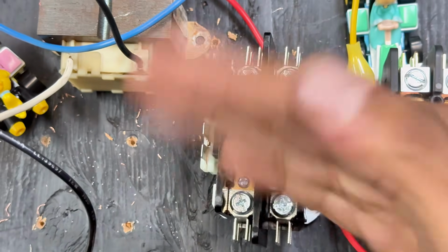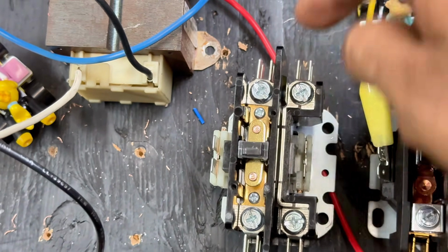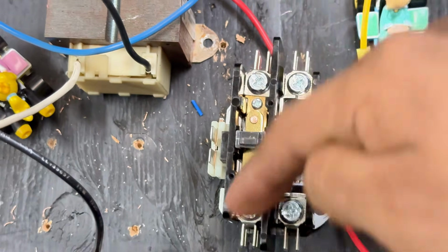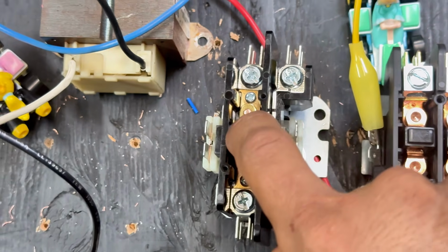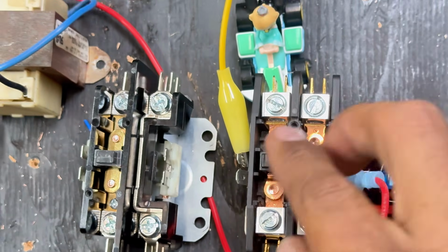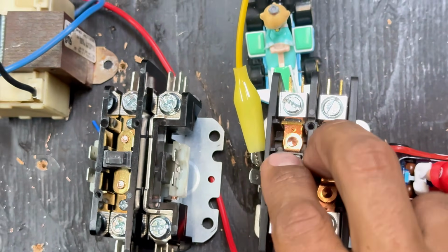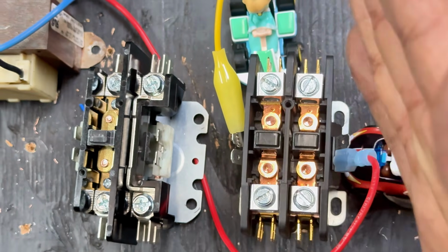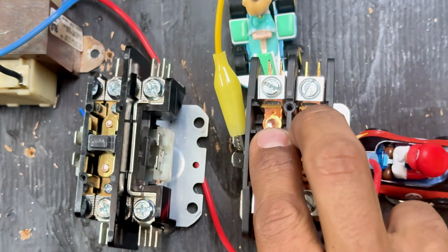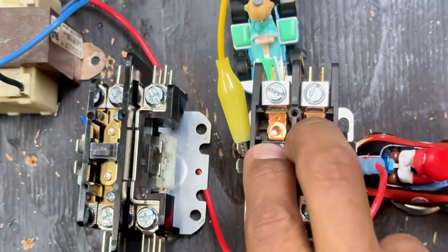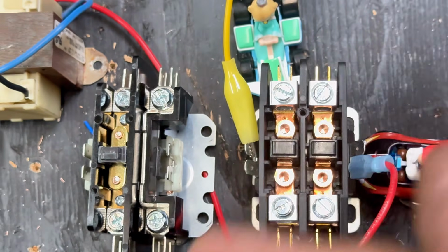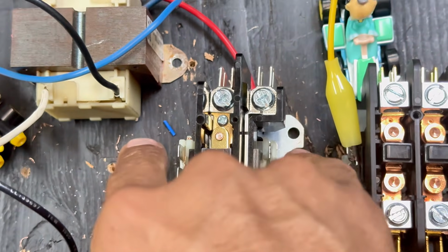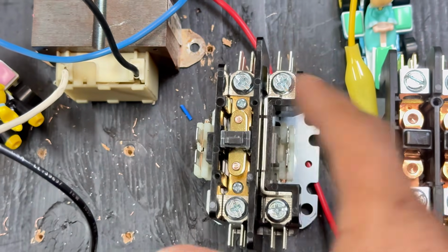And this is just a bridge. It's open, meaning that if I have power coming here, for me to go from here to here, I need to close the bridge. And that's the idea behind this. The contactor is similar to this one, but here both poles are interrupted by a bridge that's open. For it to be closed, either I push my finger and push it down, and now I have a path from both poles from here to here, or, and of course this is the way to do it, by sending 24-volt power on the side right here.